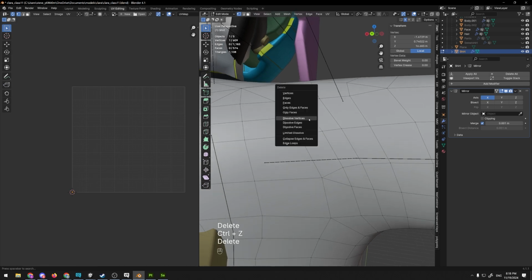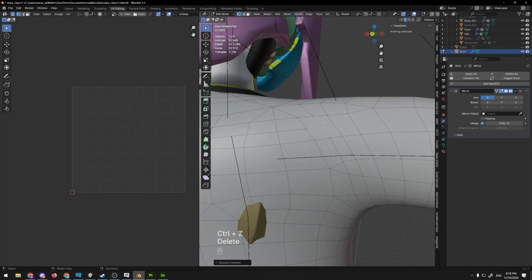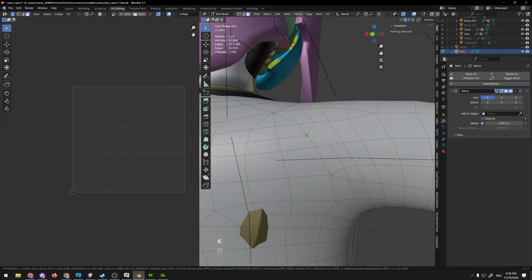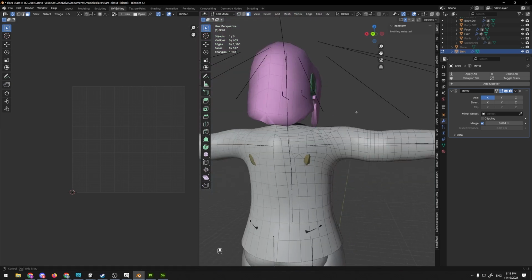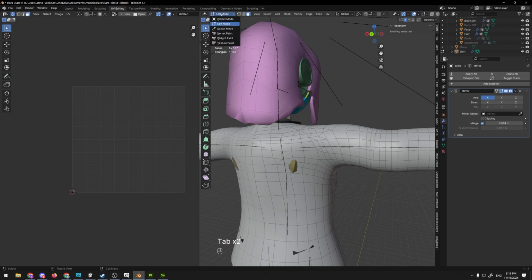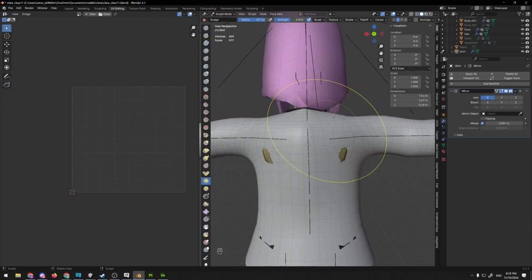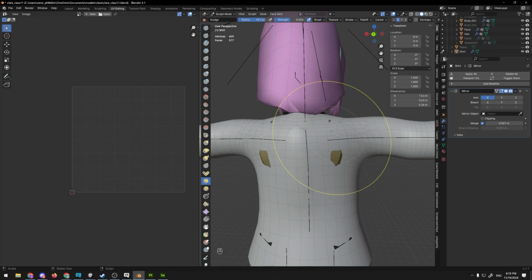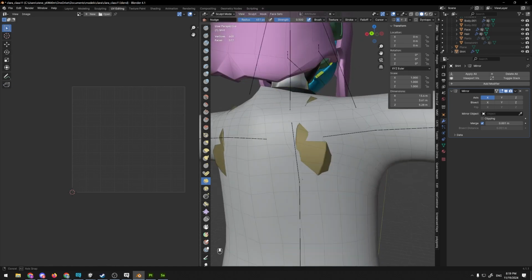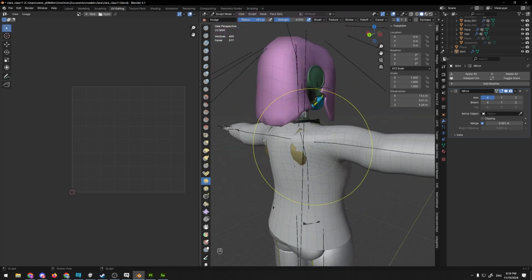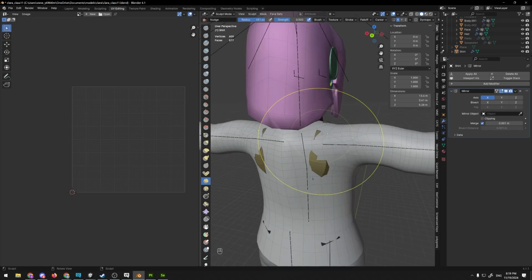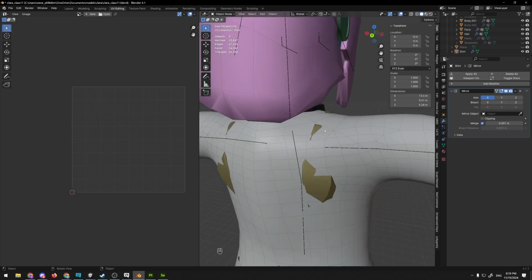So I can delete this vertex here and it just seamlessly fills in this whole face to match. And then I can do some knifing here, maybe go across or something like that. Sure, that's topology, I think. Then we can go into sculpt mode, smooth it out, and we now have more dense topology in our back. And if I continue to smooth out the back here to redistribute that topology, we now have a little bit more vertices to work with to shape our mesh.